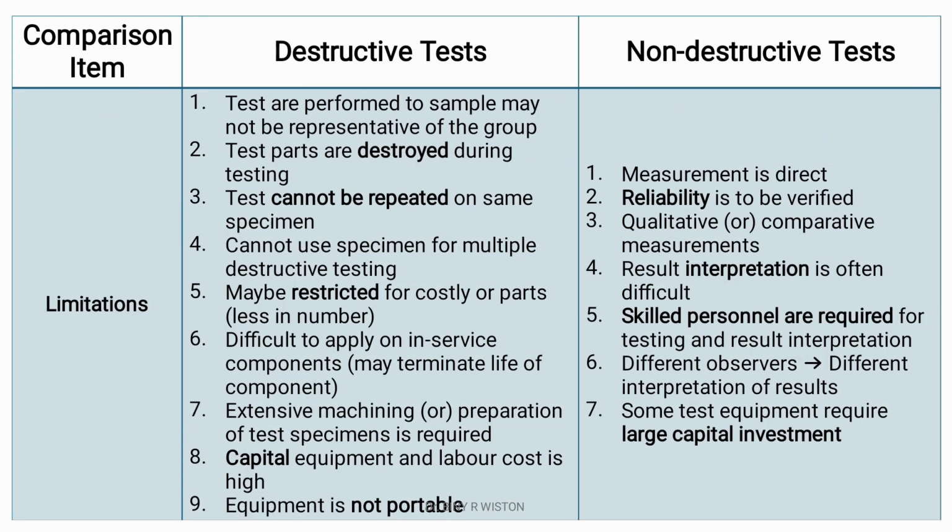Based on limitations, destructive tests are performed only on samples and components may not be representative of the group. Test parts are destroyed during the test, so usually we cannot repeat a test on the same specimen.